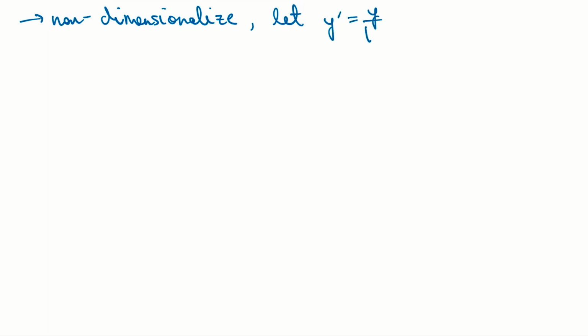Okay, now for the final simplification here, we're gonna non-dimensionalize and simplify so we don't have one dominant length scale. So watch the trick that we do here. We're gonna use h, the height. Therefore, if I scale y, I end up with a dimensionless term there, but I'm also gonna scale z, and this is just about taking an extra step here. And then u will scale to some characteristic speed that's caused by the pressure drop, and that is worth writing.